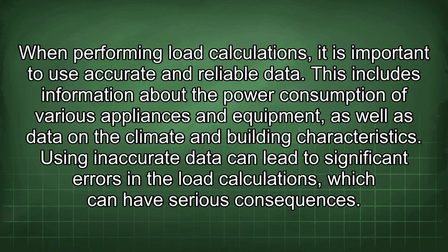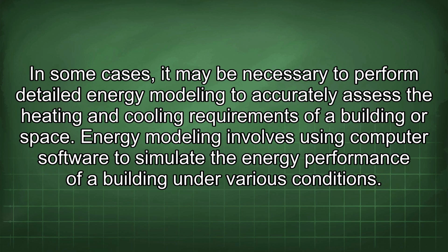When performing load calculations, it is important to use accurate and reliable data. This includes information about the power consumption of various appliances and equipment, as well as data on the climate and building characteristics. Using inaccurate data can lead to significant errors in the load calculations, which can have serious consequences. In some cases, it may be necessary to perform detailed energy modeling to accurately assess the heating and cooling requirements of a building or space.